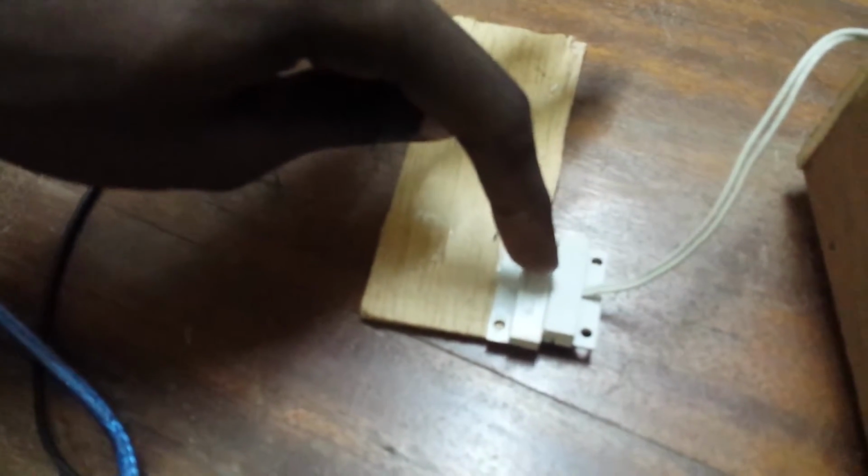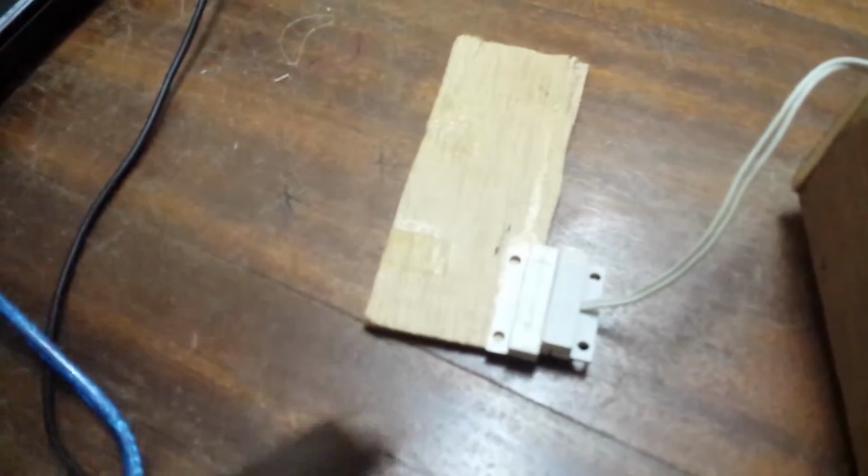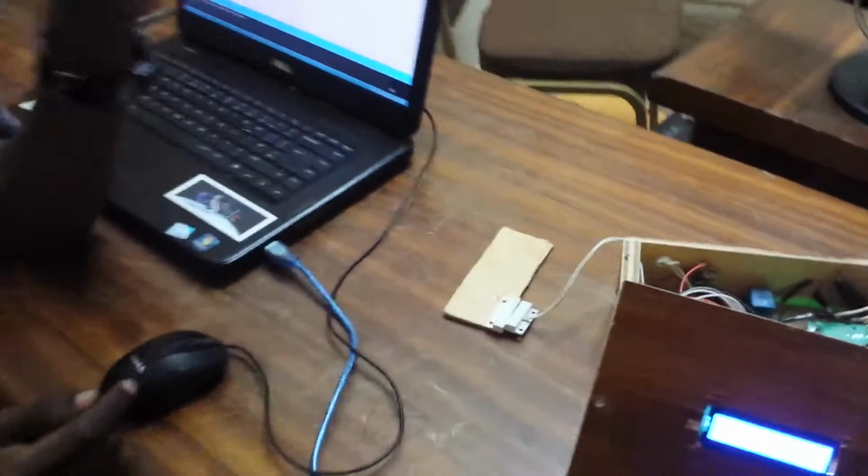And so in the first one, as my partner said, it has a security system embedded in it. And this is the reed switch that we used for the security section. So this will be attached to the door. One side will be on the rack, and then the other side will be attached to the door. So when the door is open, there will be a break in circuit, and therefore triggering will happen and an SMS will be sent to the owner of the house.